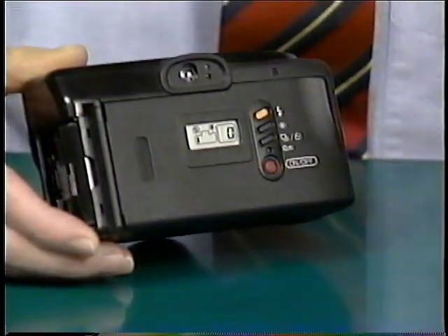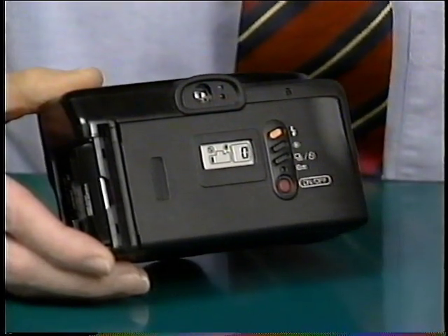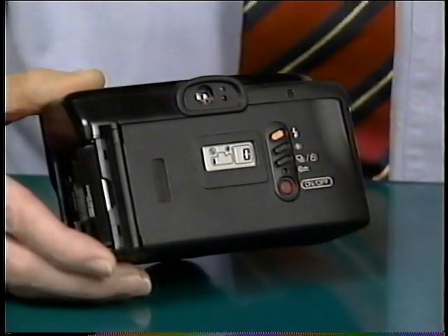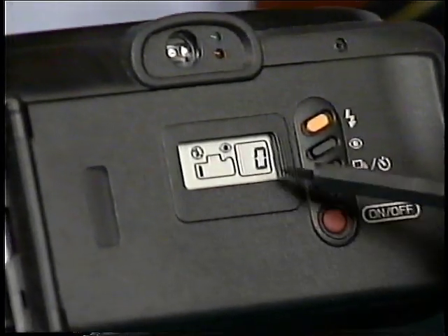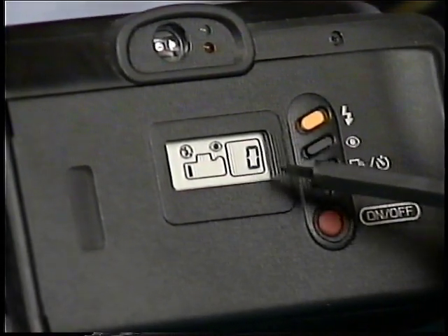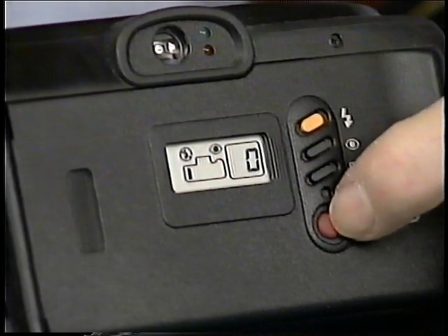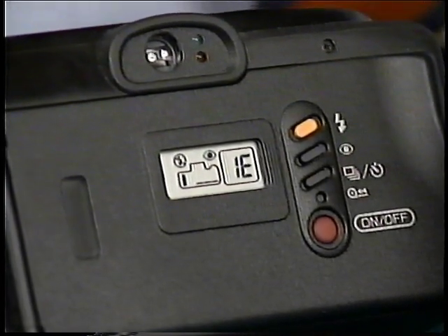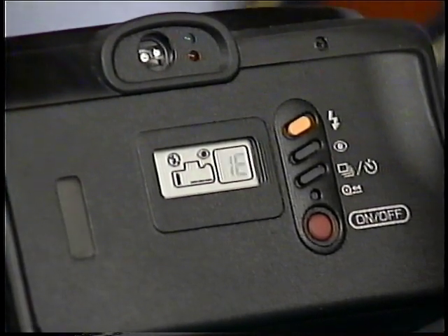If there is any type system error in a camera, they'll let you know that, and usually with an error message, usually the letter E followed by a number or possibly by another letter. This camera has booted up correctly in as much as the battery's been installed, the microprocessor has come to life, we have the 0, but when we press the main switch, in other words to extend the lens and start the camera, a problem occurs in the zooming and we get an error message.